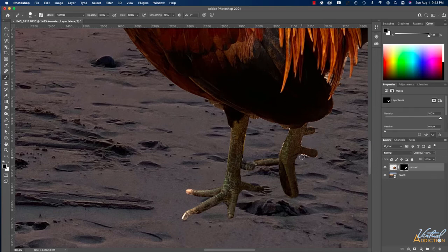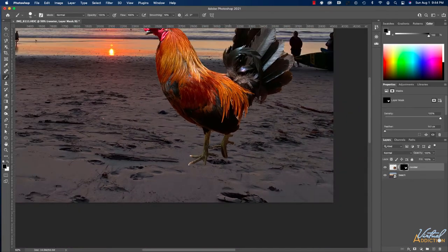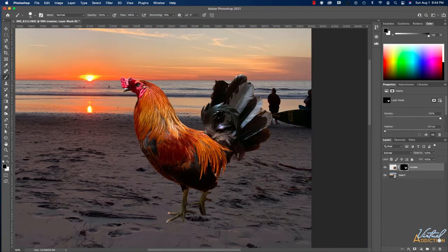So you can see how I got a little bit of the edges on these toenails and whatever. So I might want to subtract those. This is what we call non-destructive editing, in that we're not actually making any permanent changes. Like if I had just inversed and deleted, I would be making a permanent change. But because I'm doing this in the mask mode, I'm not.